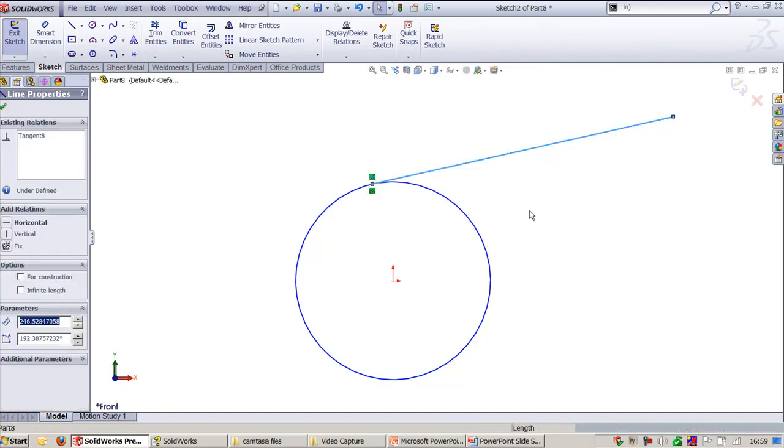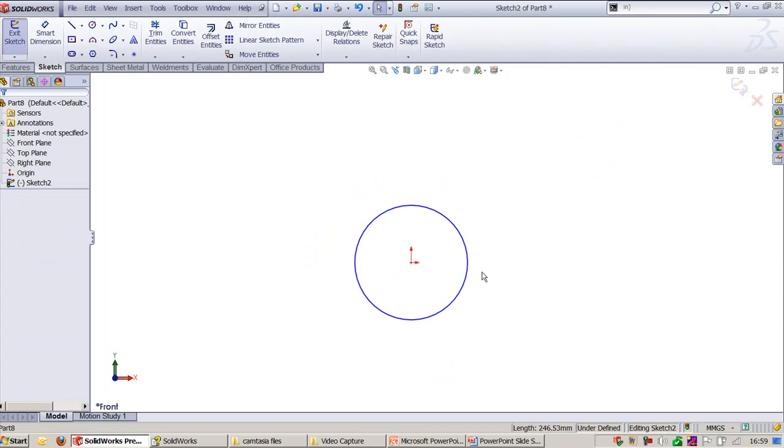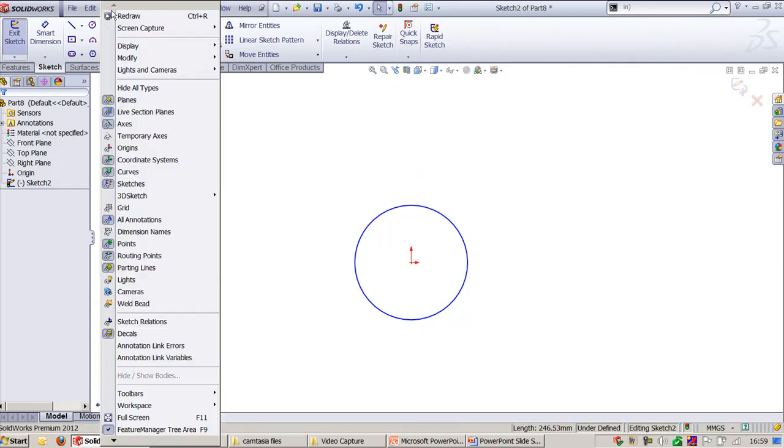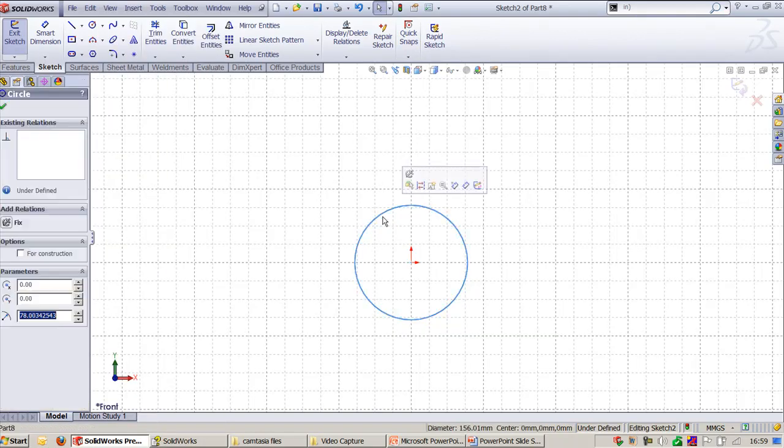This is one. If you want to create a different layout, or if I want to create a more complicated sketch where the dimension increments are 20, 20, 30, 40, in this situation I can use grid control. Means I can enable a grid. I will enable grid by going to the view menu. I will say grid. Now the grid is enabled.